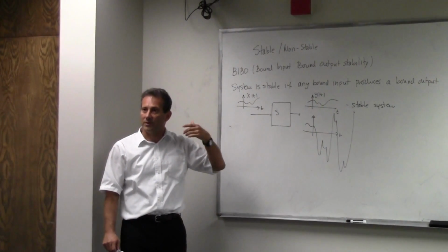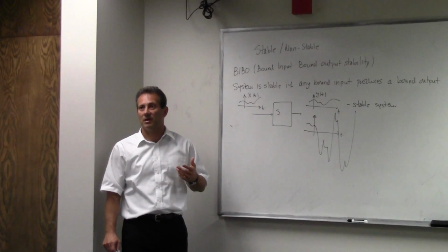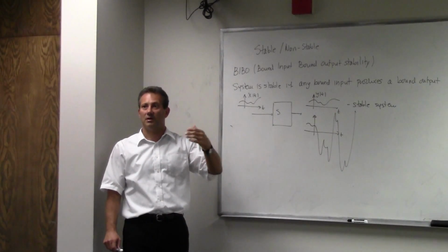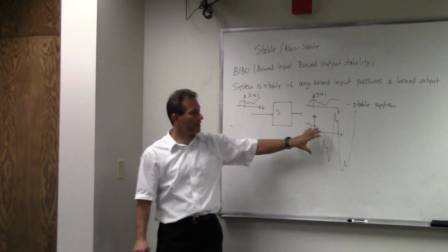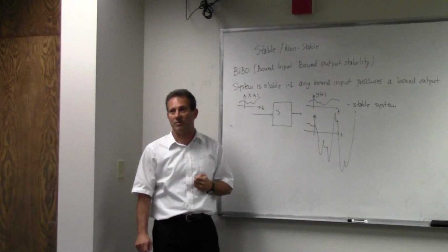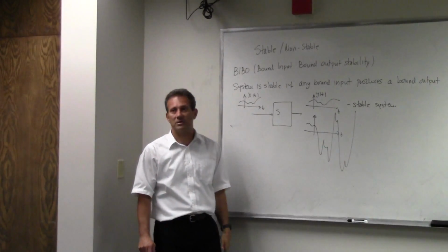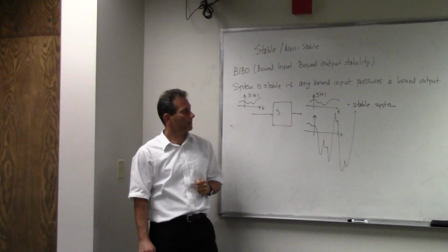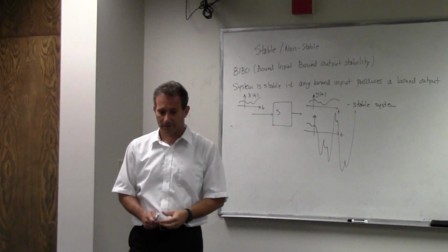It relates to, when we later on look at the poles and zeros of the characteristic equation of the system, then we're going to say, okay, if the poles are on the left-hand side, then these systems are stable. If the poles are on the right-hand side, they're unstable. And you will see that we'll go back to this, and we will discover why these systems are unstable from their differential equations. How you solve that and how you compensate for that, that's a different story. But it's a pretty, I would say, long story. There's a lot of stuff there.